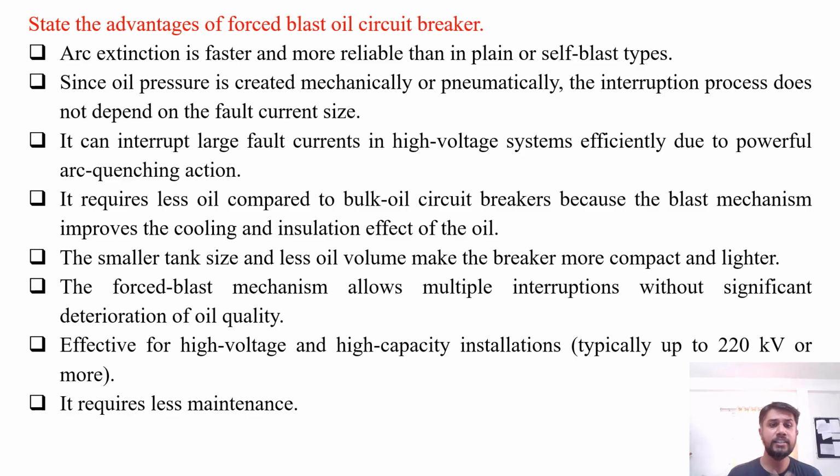It requires less oil compared to bulk oil circuit breakers because the blast mechanism improves the cooling and insulation effect of the oil. The smaller tank size and less oil volume make the breaker more compact and lighter. The forced blast mechanism allows multiple interruptions without significant deterioration of the quality. Effective for high voltage and high capacity installations, generally about 220 kV or more. It requires less maintenance. So these are several advantages of forced blast oil circuit breaker.